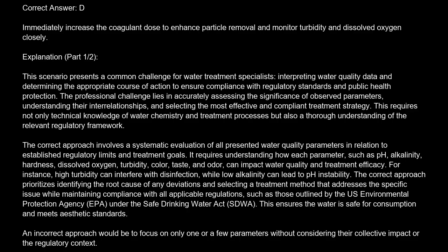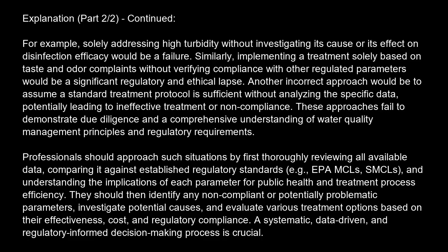An incorrect approach would be to focus on only one or a few parameters, without considering their collective impact or the regulatory context. For example, solely addressing high turbidity without investigating its cause or its effect on disinfection efficacy would be a failure. Similarly, implementing a treatment solely based on taste and odor complaints without verifying compliance with other regulated parameters would be a significant regulatory and ethical lapse.